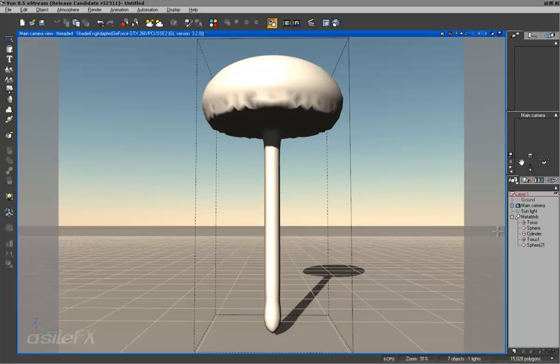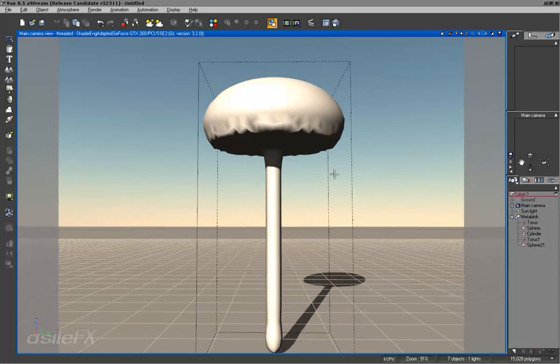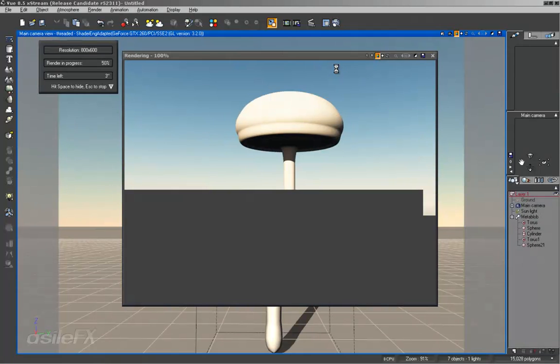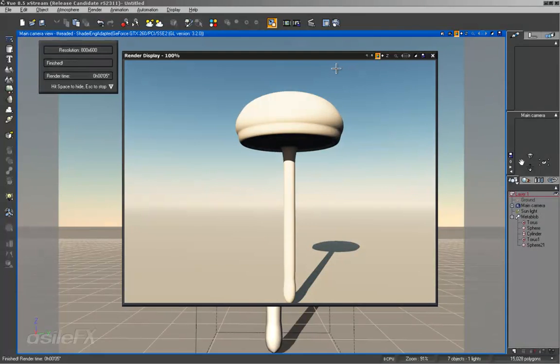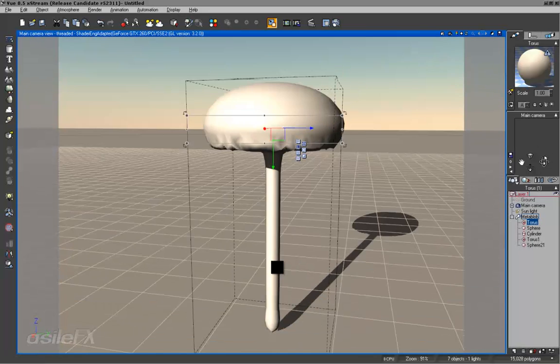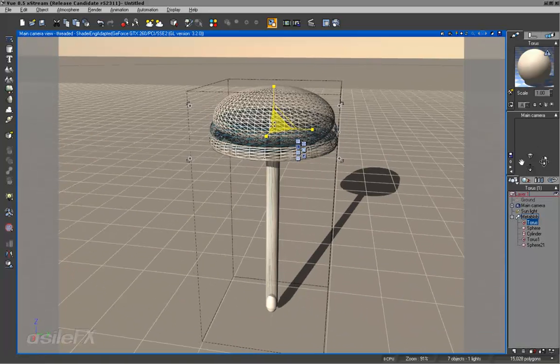Now the preview we're getting shows a lot of torn edges on the bottom. When we render this as a metablob, none of that is there. But once we bake the object, which we're pretty much going to have to do, that is going to show up. So basically we're looking at the preview as what's going to end up being the baked object.